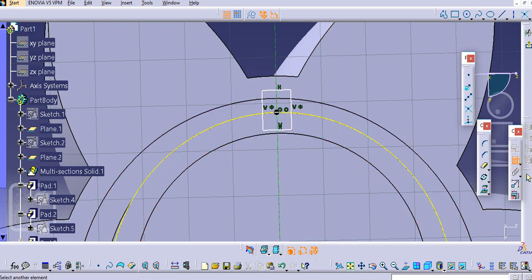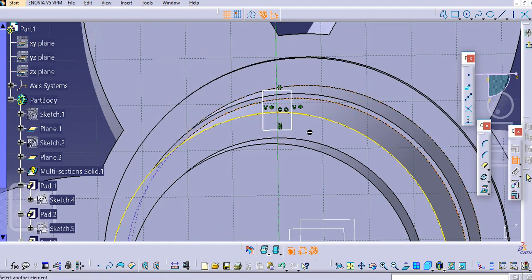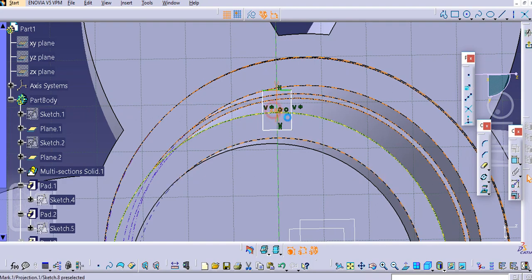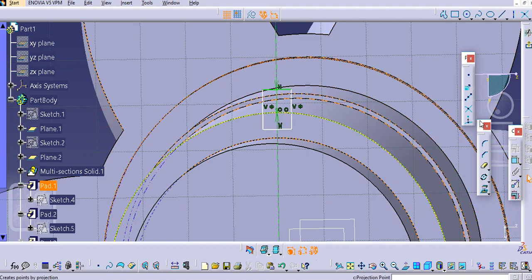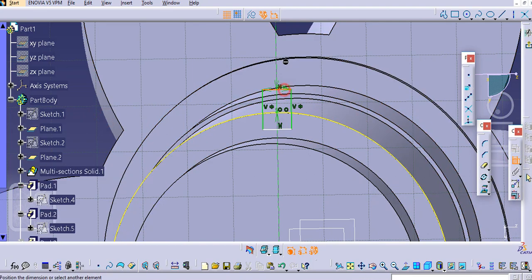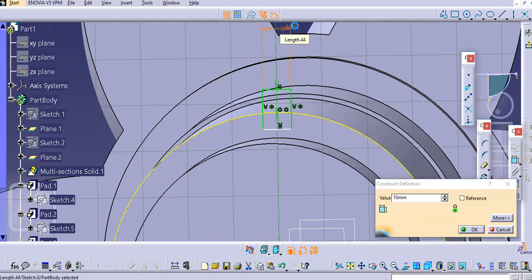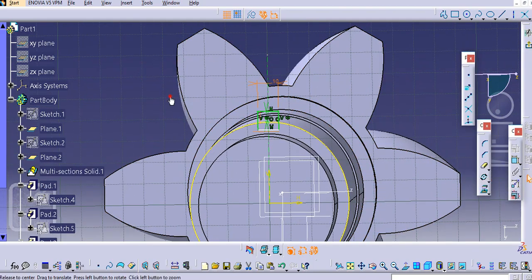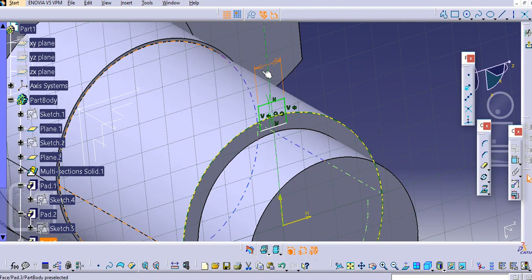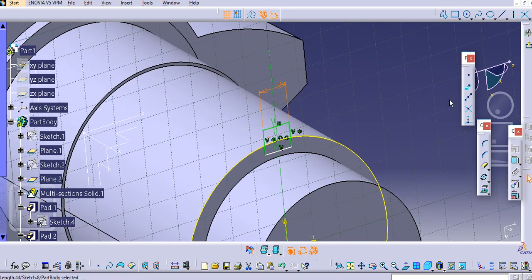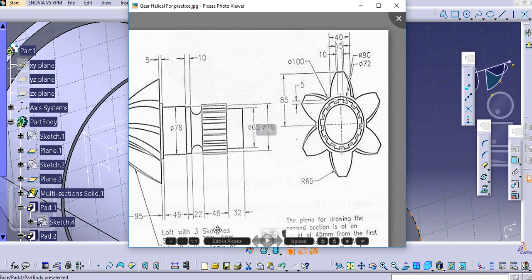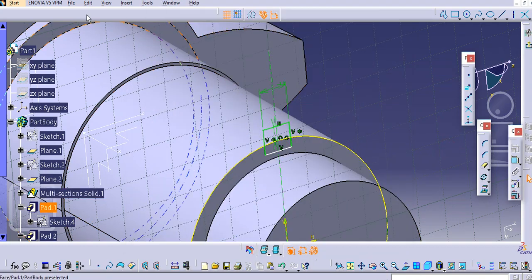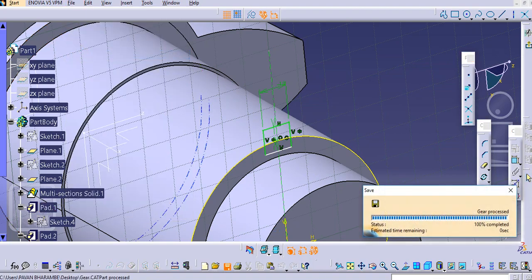and now we will provide a dimension for this vertical line and this point here. This will be 5 mm and the horizontal dimension must be 10 mm. So just provide a 10 mm dimension. So now you can directly extrude this. So just check this first. The extrusion, how much extrusion we need is 48 mm. So again we will save this,